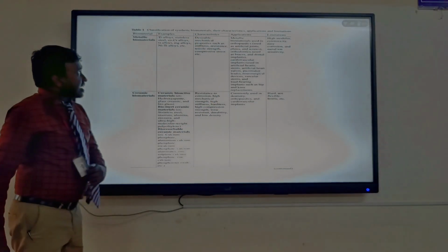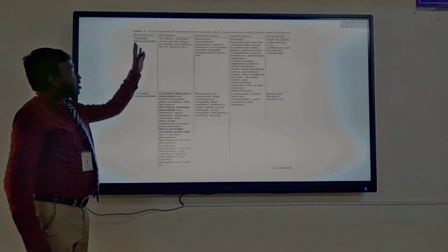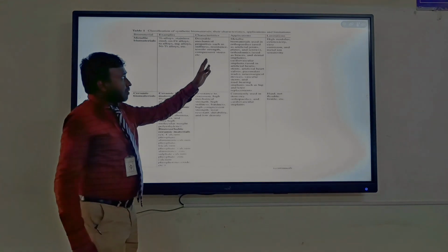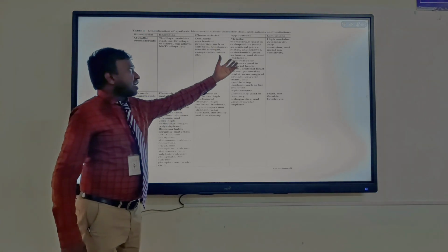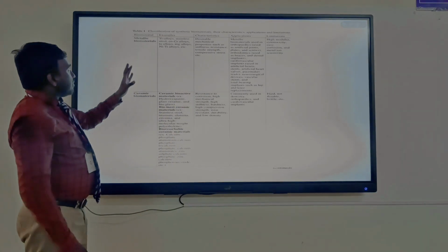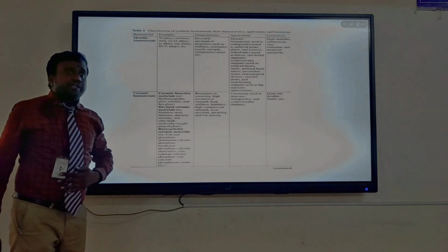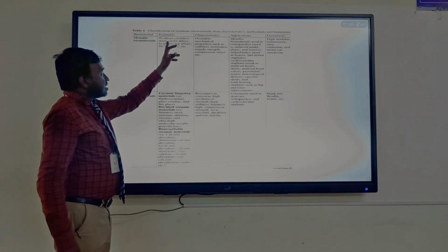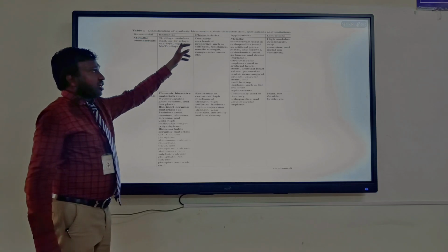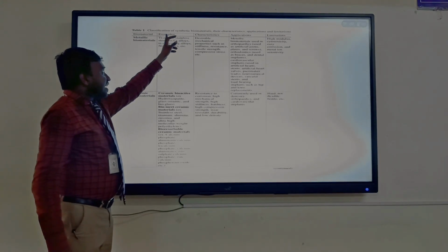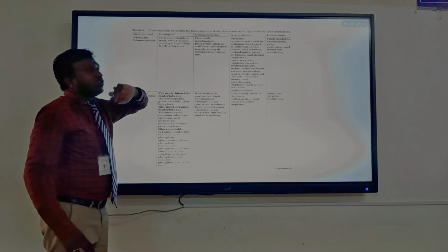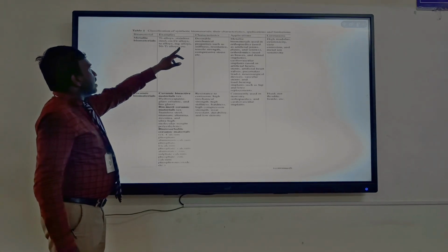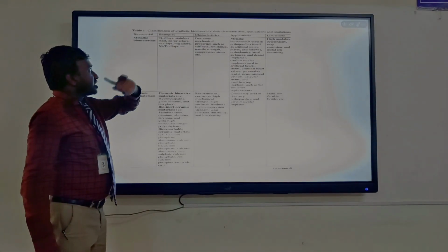Okay, these are some of the prominent types of biomaterials used in industries, the reasons for using them, and some of the applications. The first category we are going to see is metallic-based biomaterials. In this we use titanium alloy, stainless steel and, as I discussed, cobalt chromium alloy. Titanium alloy and cobalt chromium alloy are the most commonly used alloys in the metallic biomaterial industries. There are also magnesium alloy and nickel titanium, which is a super alloy.